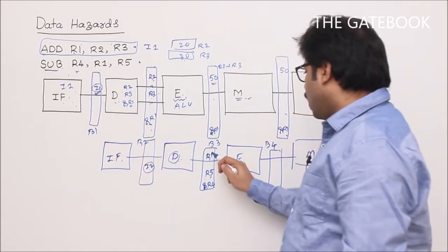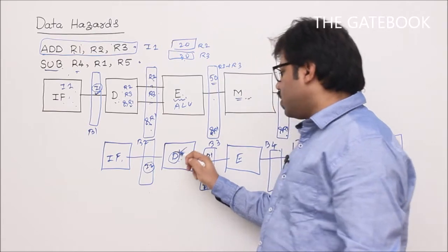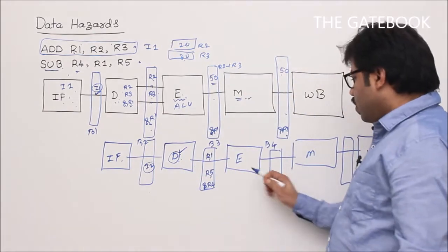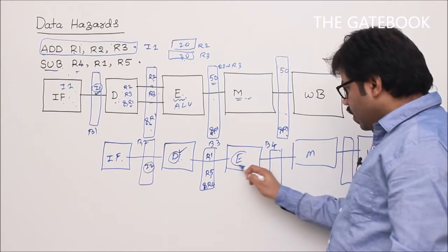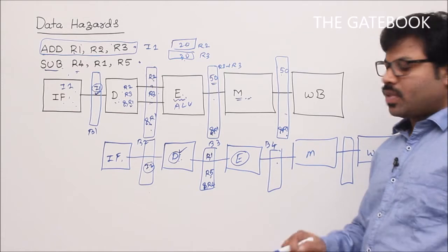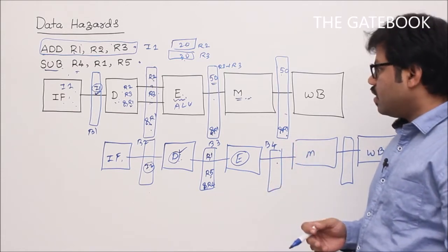Now the content of R1 and content of R5 I take after the decode stage. In the decode stage, I will be taking from the register file. So now slowly you understand here, if you execute, then R1 plus R5 should be added. But here is the problem. Now if you see carefully, there is a mistake we are doing. What is that you see?